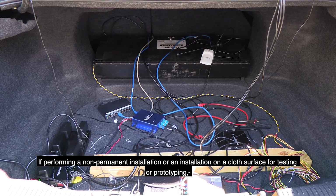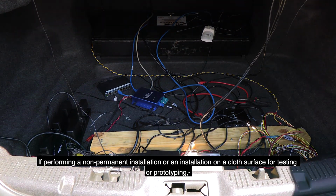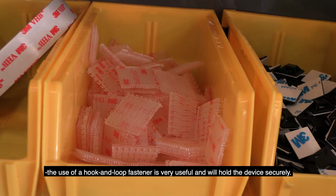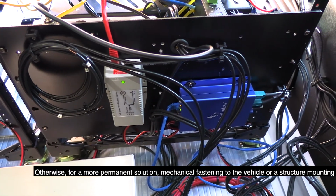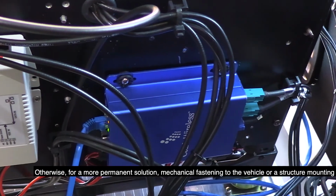If performing a non-permanent installation or an installation on a cloth surface for testing or prototyping, the use of a hook and loop fastener is very useful and will hold the device securely. Otherwise, for a more permanent solution, mechanical fastening to the vehicle or structure mounting in the vehicle is preferred.